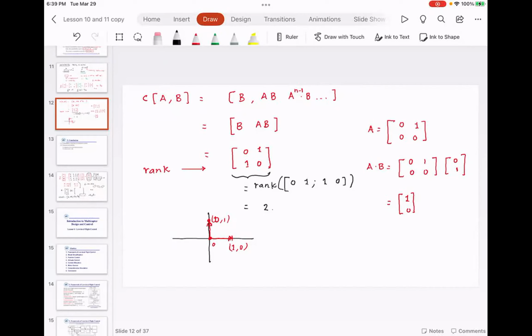If you want this quadcopter to go forward, you will have to pitch it down or pitch it up, and only then can it go forward and backward. That is where the mixing algorithm comes into the picture. Everyone understood this? So controllability means you are trying to influence all the states of the system by external torque or force. If the external force or torque cannot reach some state, you change the dynamics.